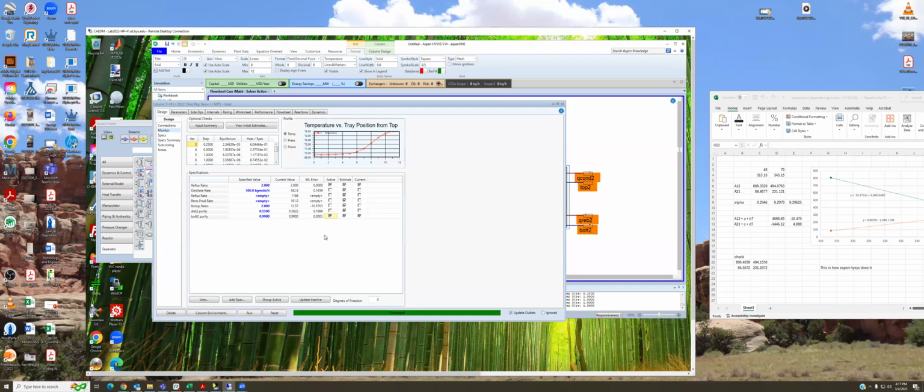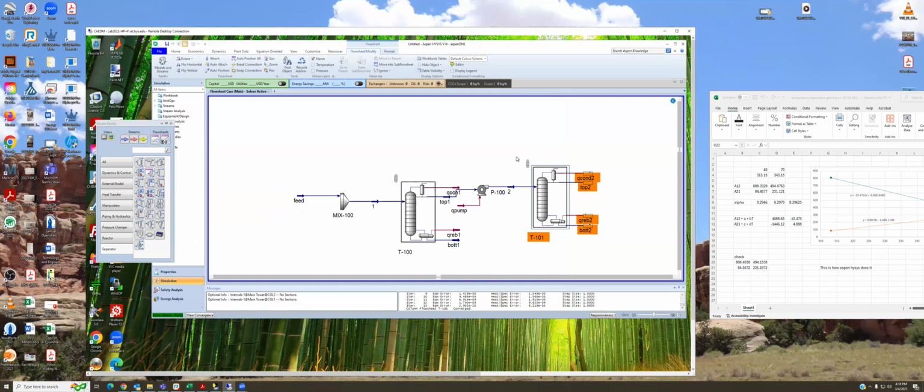Again, we've got a pretty good temperature profile, reflux ratio of 2, boil-up ratio is pretty high, 12.5. We're getting our bottom purity. Let's see if we can sneak that up a little bit more, like we did with our first column. Okay, so we got both columns operating at 0.995 purity of our product stream. Okay, that's good. Now, as we've said before, we want to recycle this top azeotrope back, combine it with the feed to the first column.